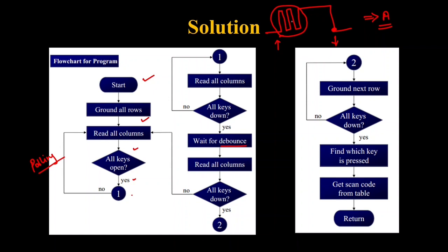So how can we eliminate this debounce condition? We connect a capacitor to that, so the capacitor gradually charges and reaches its maximum point, and then we can release it, right? The connected capacitor charges slowly, reaches its maximum, and after that it gives the output. So finally from this I can understand this is the character A being pressed, till it crosses the level of those exact points. We have said it is 0 to 0.8, and after that 2.5 to 5 volts, in terms of representations of zeros and ones in your 8051.